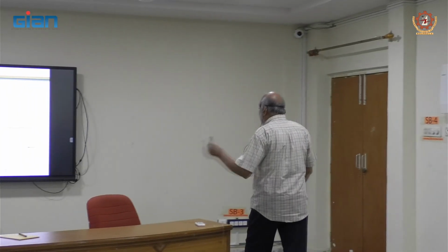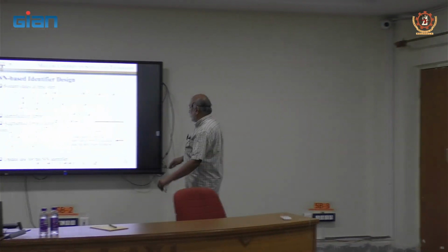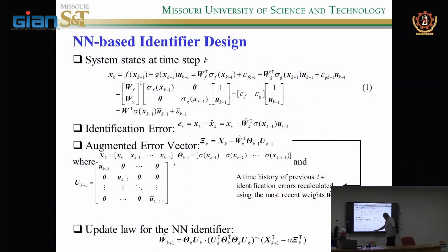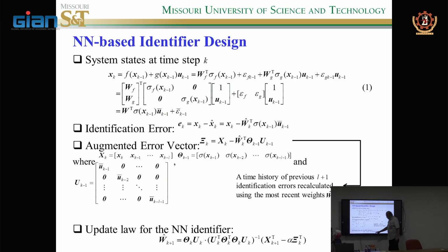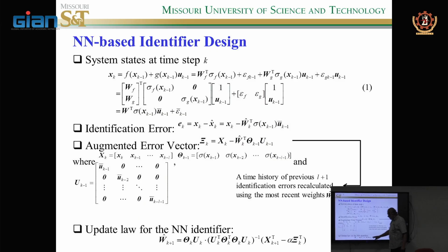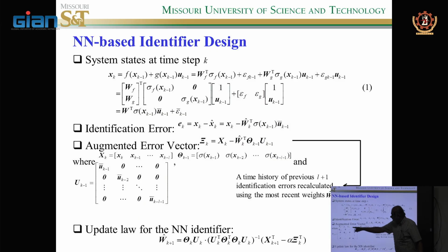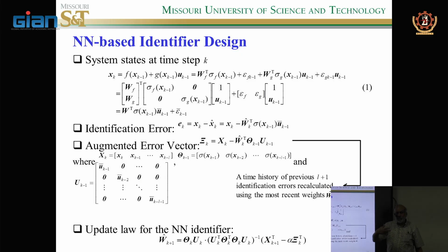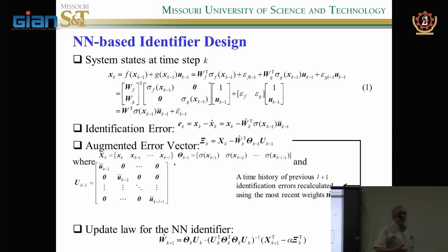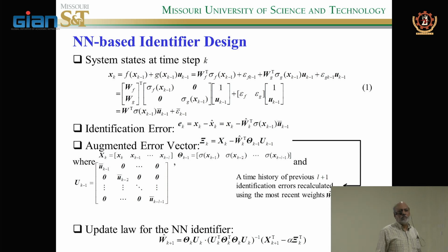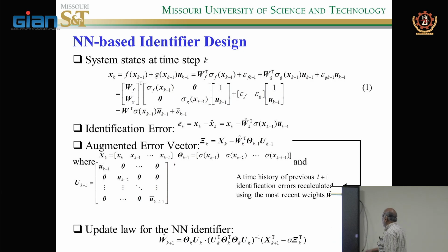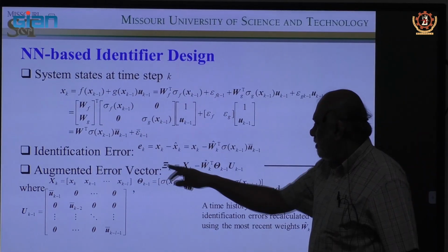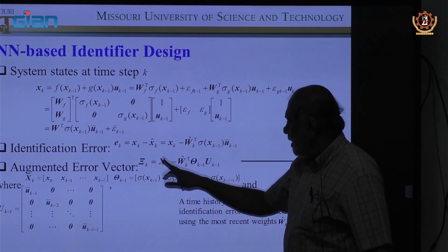That's why I said equation 2. It is a matrix, and it has to be invertible. This can't be done unless you construct that history. That history makes that matrix invertible, which is what we call persistency of excitation. And you see that all this is also a vector based on the history.